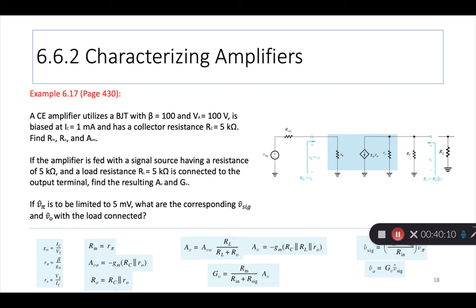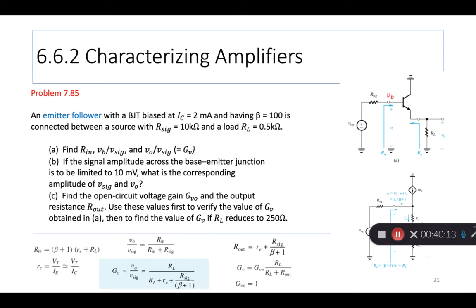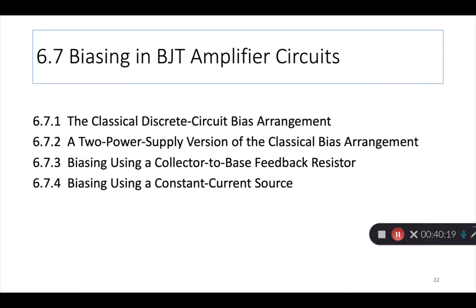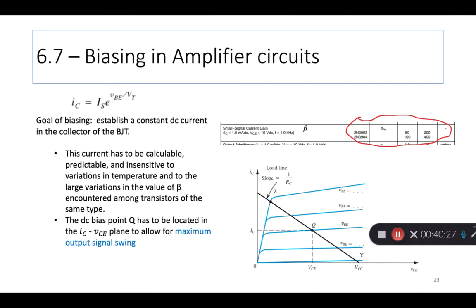All right, we have many numericals, exercises, problems that we'll come back to. There's 5 more minutes to finish up some important stuff here. Biasing, right? I think we've already studied biasing. Biasing is to establish the proper Q point, right? So that the amplifier can work on either side. Remember all those drawings I showed you? The signal comes in on the input from here, but you don't want to go into the nonlinear portions of this characteristic.